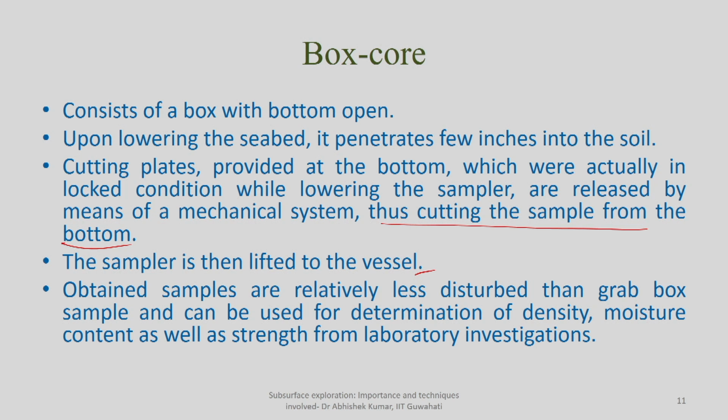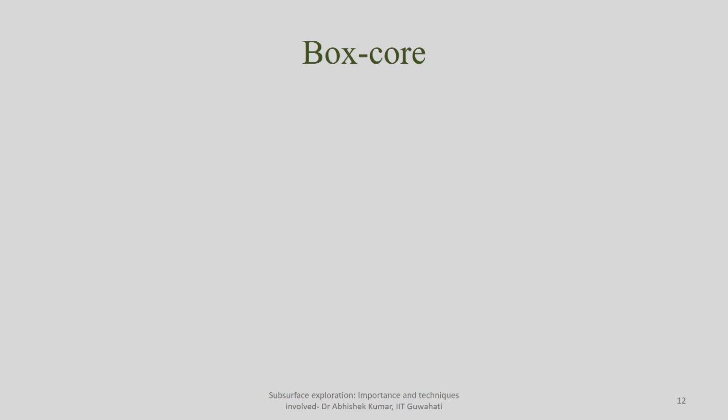Now, the samples obtained in this case are relatively less disturbed in comparison to the grab sampler, and thus can be used for determination of in situ density, moisture content, as well as strength characteristics. Whatever sample you have collected, you can use for necessary laboratory investigation, because that is how you will get an idea about what kind of medium is available beneath the surface and what its strength characteristics are.